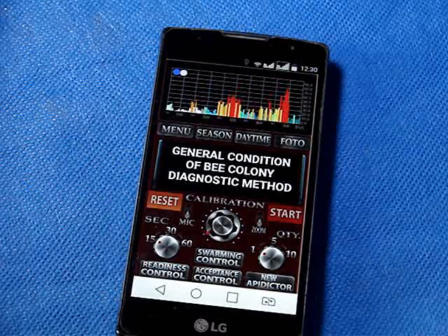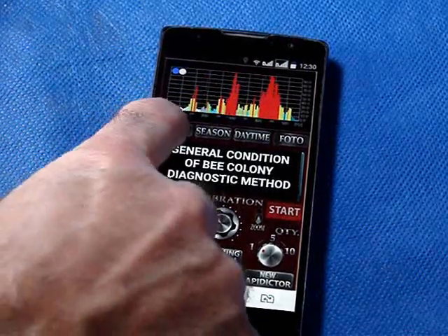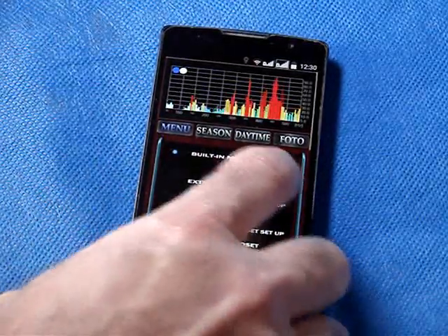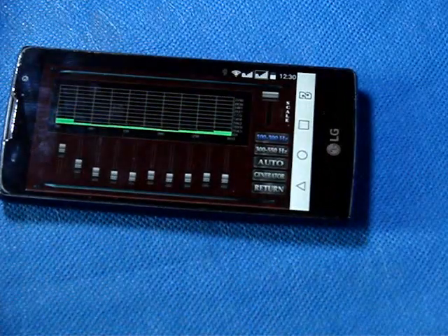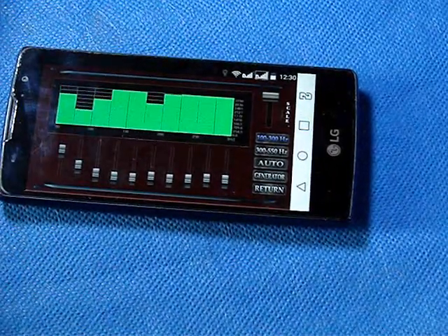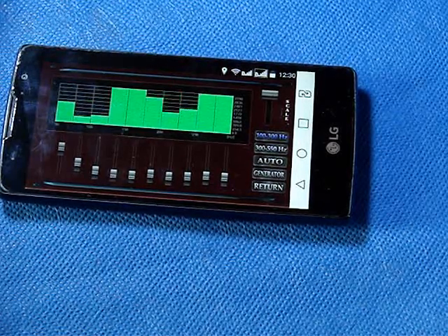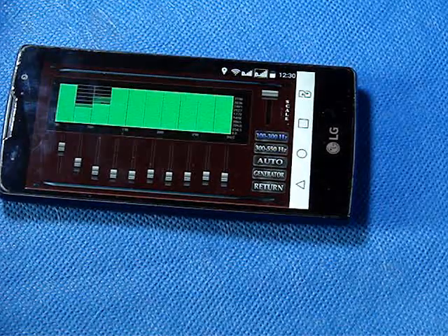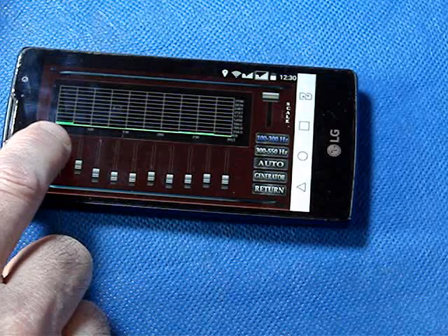But in principle, if the speakers are not perfect, and they are usually not ideal, then we need to make another stage of tuning, about which we in principle told you. So, it would be necessary, in the settings section of each microphone, in complete silence, to see how the last left columns of the equalizer diagram behave. These 2 or 3 columns show compensation by our program of the poor quality of the microphone. But, unfortunately, the loudspeakers of acoustic systems are of poor quality too, and this adds distortion too. Even in our case there is a small bar on the diagram on the left, and we must equalize it with the rest of the diagram in complete silence.